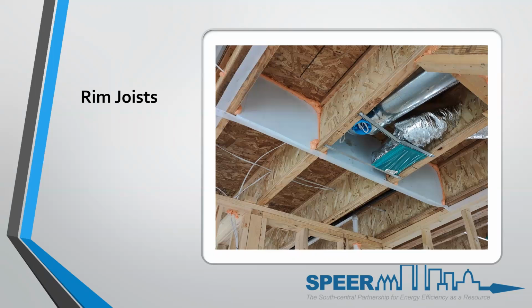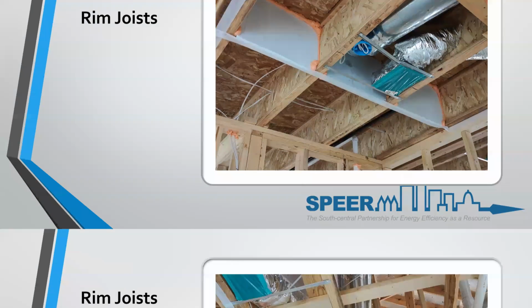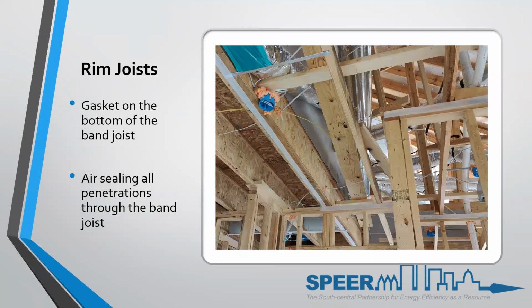This is the correct way to do it. It's rarely done to this level of air sealing, but it's the correct way to do it. Using an IR camera with the blower door, you will see all of these areas of deficiency. If that gasket's missing, if that band joist is missing, if poly seal around the band joist is missing, you will see air movement through there with an IR camera. So same thing with that.